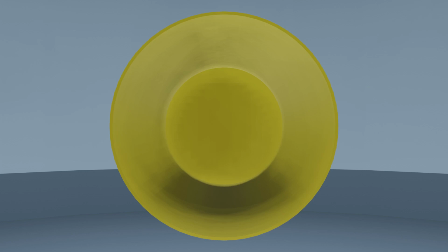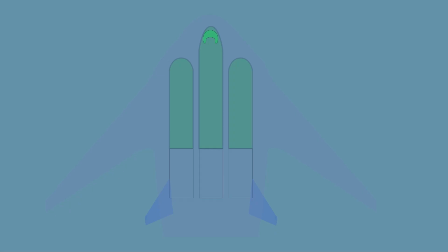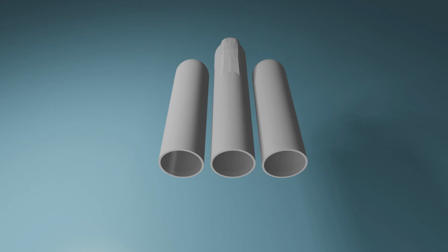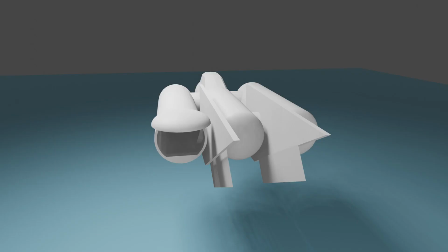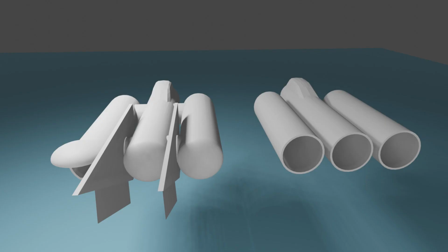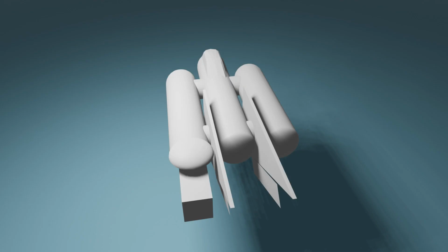But for a cargo airplane, the cargo could be put in three tubes. The tubes would be pressurized, and the rest of the aircraft would be unpressurized. The central tube would be extended to provide a crew area and a cockpit area. So the cargo would be shipped in a pressurized hold, but the bending stresses would be avoided. The cargo could be shipped in objects that are the size and shape of a 40-foot cargo container.